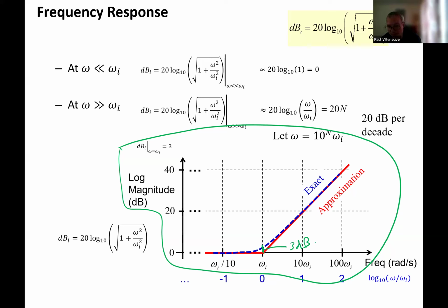But if you're using an approximation and you want to get pretty accurate results, what that tells you is you want to be well away from your break frequency, so that if you're relying on it to be giving you really good results at those frequencies, you need to stay well away from that. So perhaps you would do a high pass filter or a low pass filter, and you say, this works for a break frequency at, let's say, 500 kilohertz, but I'm going to be well away from 500 kilohertz to have it either amplify or attenuate the signal.